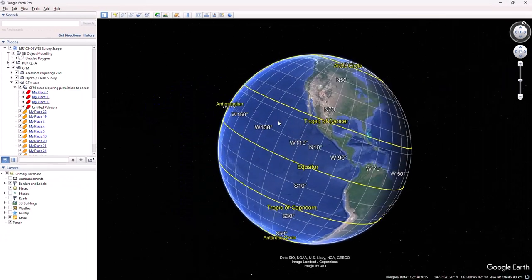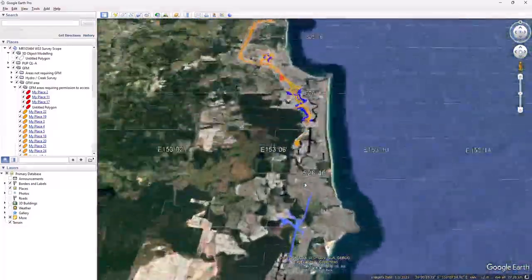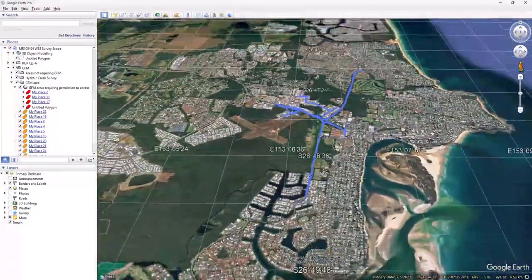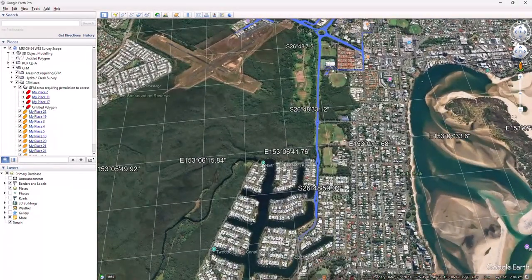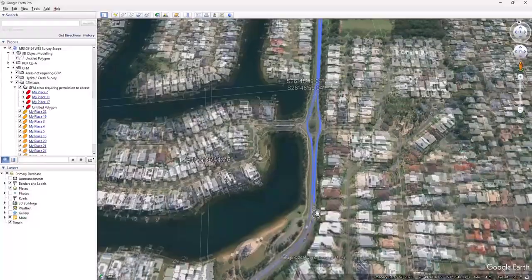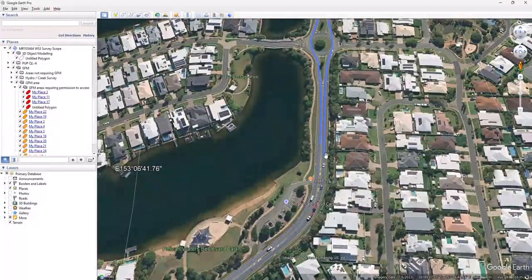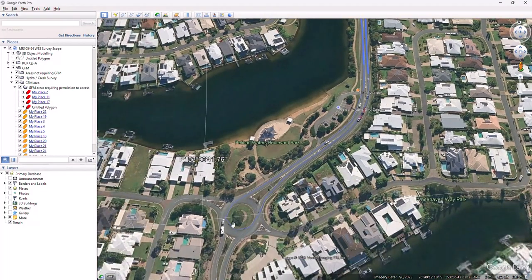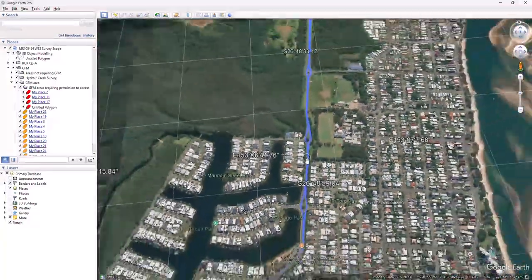This is automatically downloaded onto the drive. You can see here, this is what is being driven. I'll show you in a different video the TMI, or Trimble Mobile Imaging, workflow there. But you can see, if you zoom in, where the line is thick is where we've captured LiDAR and imagery, and where the line is thin is the approximation of what we've captured in the mission.